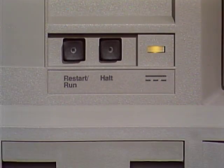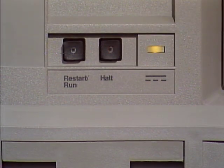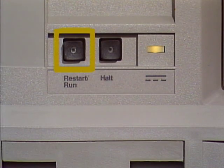Next to this indicator is the halt switch. It is a momentary switch that halts the system when pushed. It contains a red LED that is illuminated when the halt button is pushed in. The push button to the left of the halt switch is the restart run switch. It is a momentary switch that resets the system and initiates the system's self-test diagnostics when pushed. The restart run switch contains a green LED that indicates the system is in the run state when illuminated.